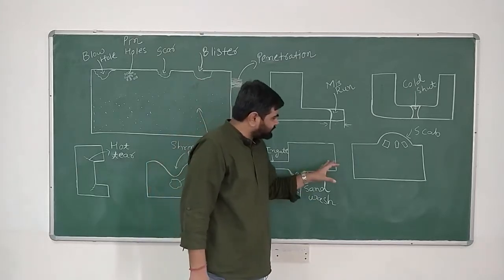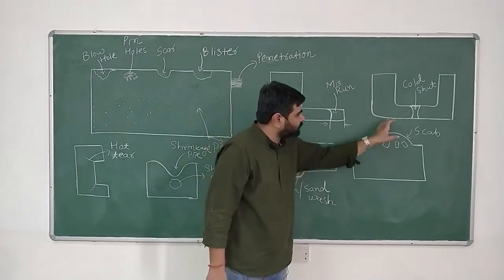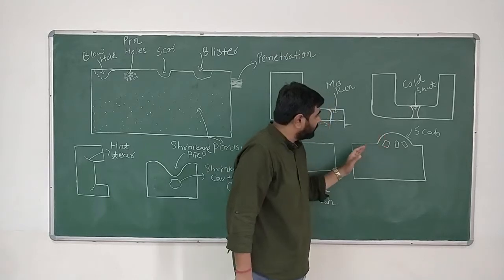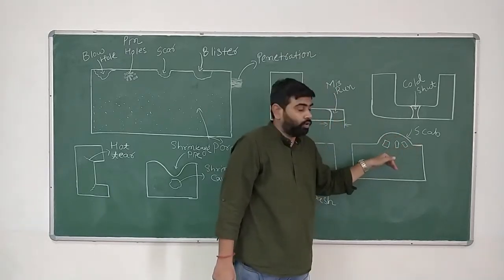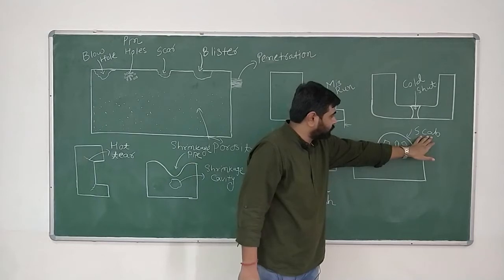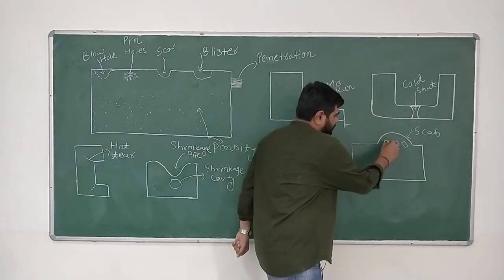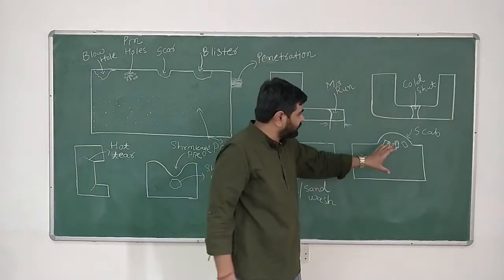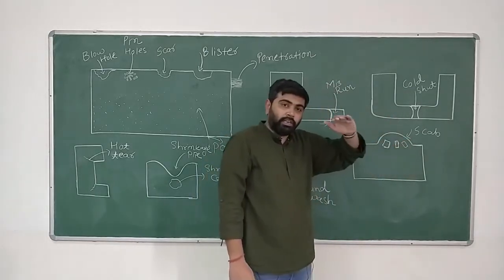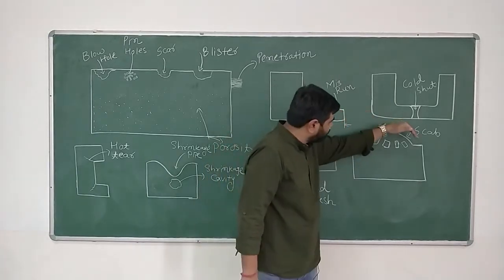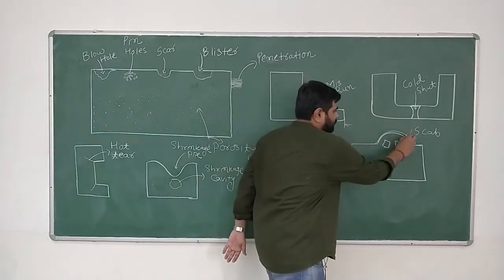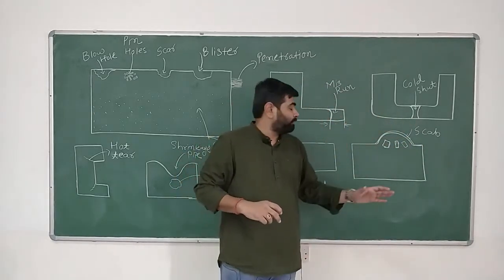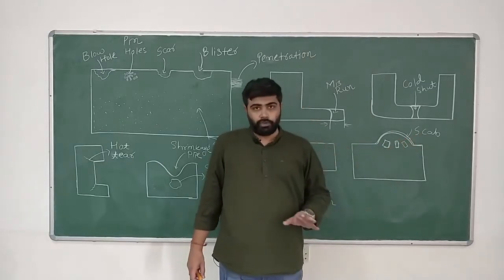Now, a defect very similar to the wash, when it happens on the top surface, which means when particles of liquid metal enter the top surface of the mold, a defect like a scab is produced. And all these random shapes that you are seeing are nothing but molding sand. So when the top surface of the liquid metal goes like this into the mold surface, and the sand particles are left below that, a defect like a scab is produced.